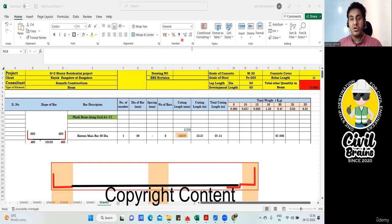Else you can do another way of lapping. I'll go with only one same color. Again, you'll bring your bar like this. You'll bring the bar up to here, and the next bar you can lap here. So you lap the bar here and lap it like this. This portion you are going to lap like this. Take it straight and then do it like this. You're getting my point?